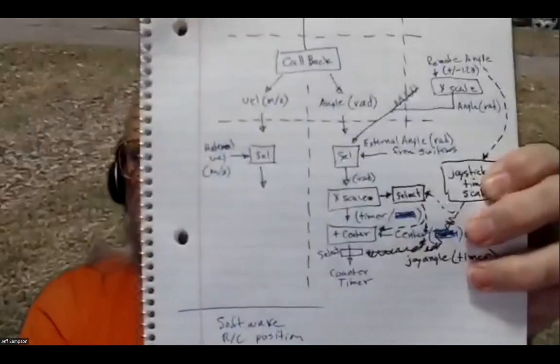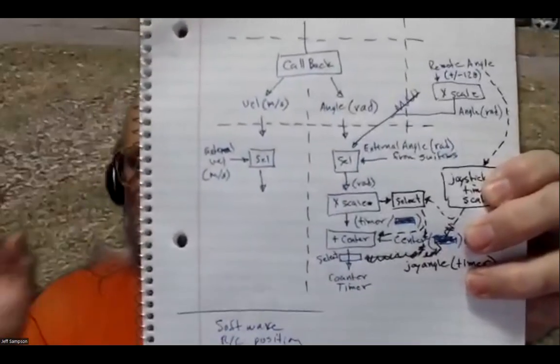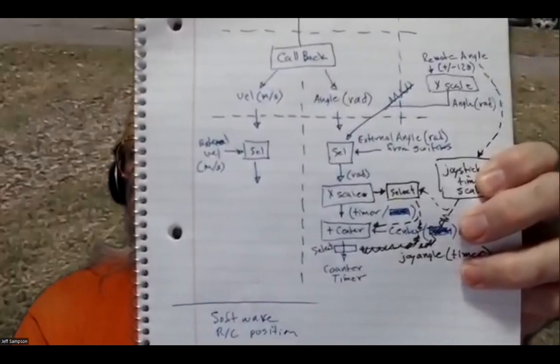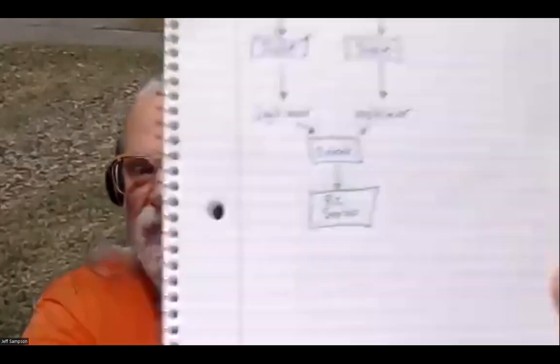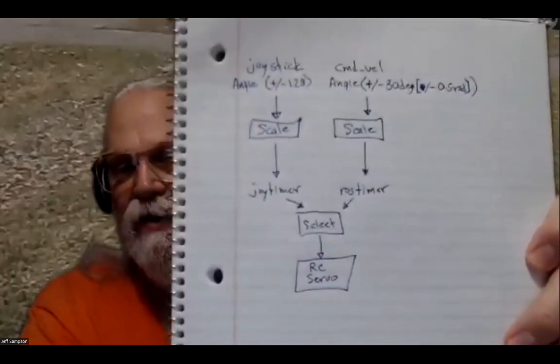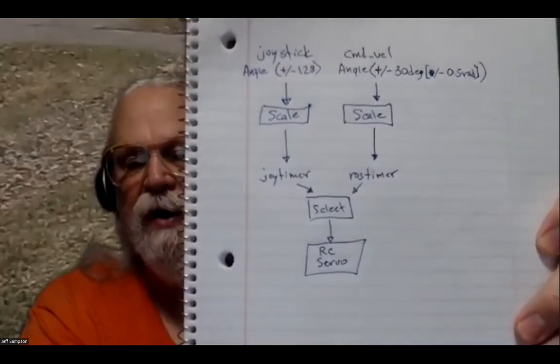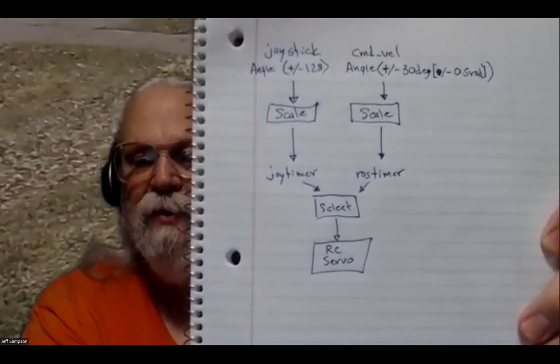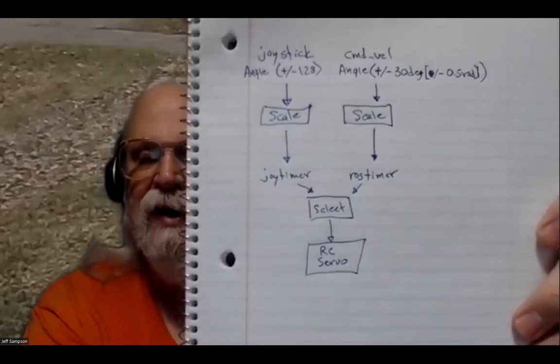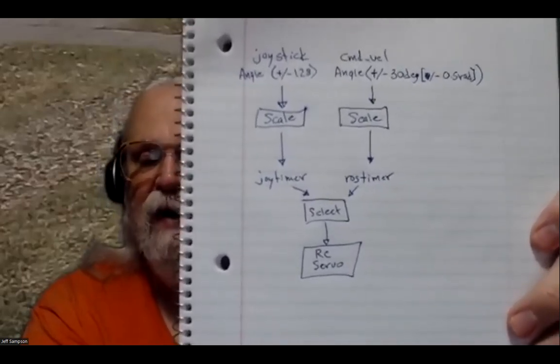And that's where it'd be handy to have a piece of software where I put down blocks and hook them together, and then drag the block without having to redo it. Then I went back and said, okay, now taking concepts. This presentation method isn't best either, but here I've got my joystick coming in. I can scale that to an angle. And on the right hand side, it says command velocity. It's coming in as an angle, and then I scale that.